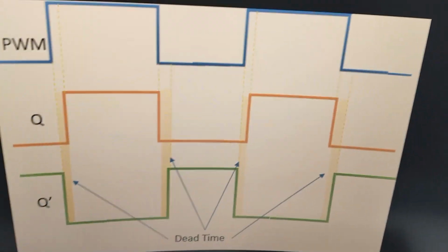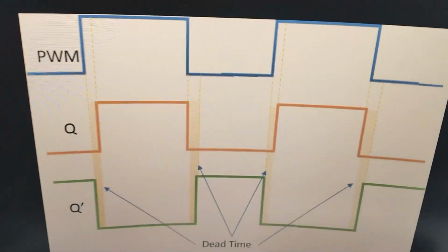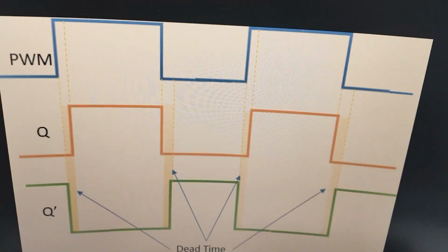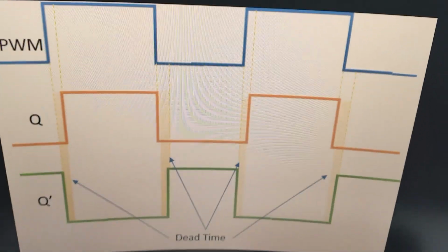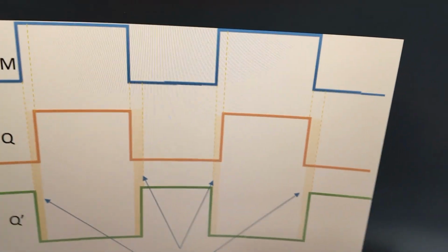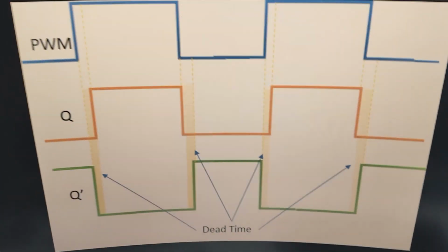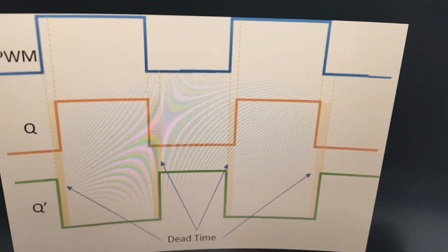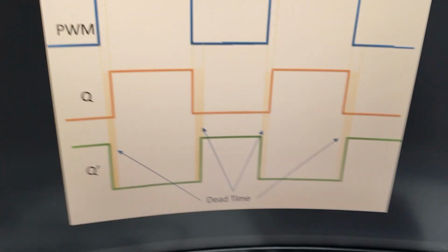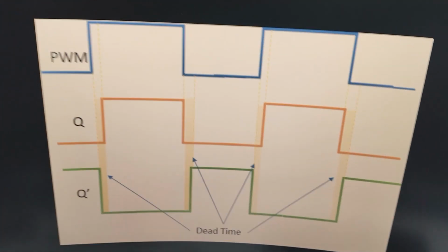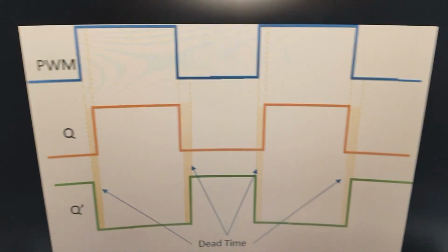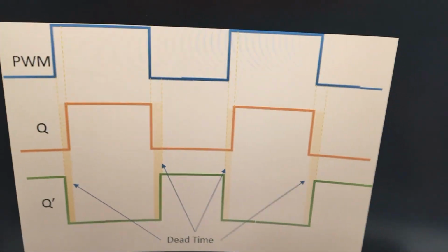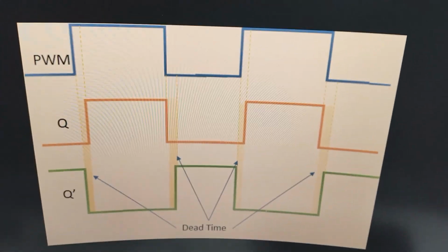In the earlier video, I used the TL494 for the analog implementation, and the TL494 does have a push pull output mode, and it does have the dead time control pin, so you can do it in the analog way also. But it still has some temperature sway and all of that, and you can't have very precise dead time. In code, these things run much faster, and after all, they are logic devices, so if you use a digital implementation, you're definitely going to have more accuracy. So that's what we're going to do today.